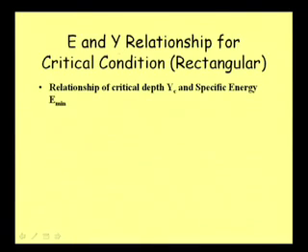So, at critical condition, can we have a definite relationship between this specific energy and the depth? Well, let us just explore that. In this slide we will be discussing the E versus y relationship for critical condition, and we are discussing this for a rectangular channel, as we are starting with the rectangular channel.